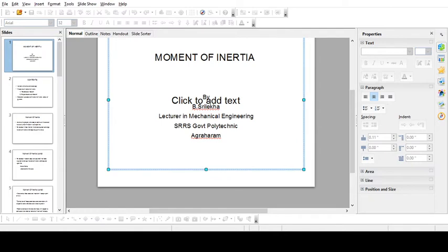Next, Iyy is nothing but I AB here. So Iyy is equal to I AB equal to pi r to the power 4 by 8, or pi d to the power 4 by 128.